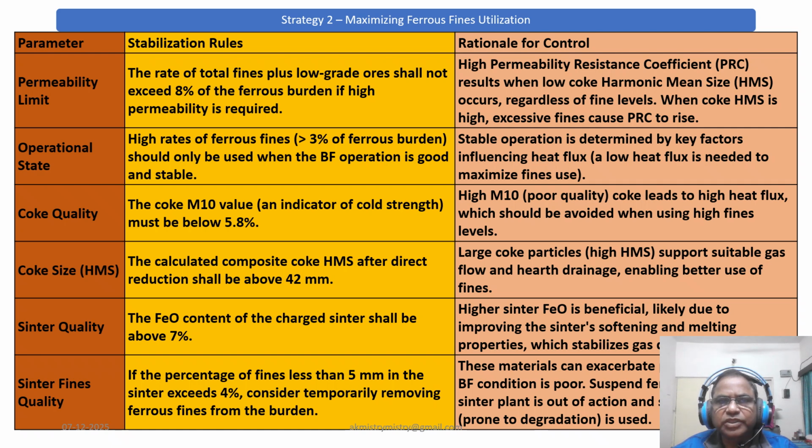Ferrous fines utilization should be suspended if the sinter plant is out of action and a stockpiled sinter, which is prone to degradation, is being used, because this material can exacerbate process upset if the blast furnace condition is poor.